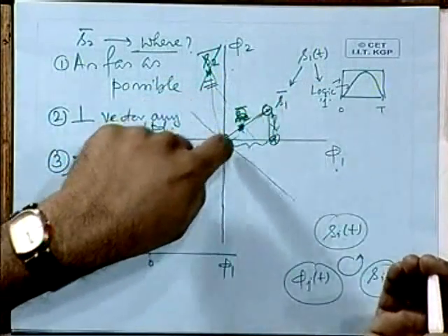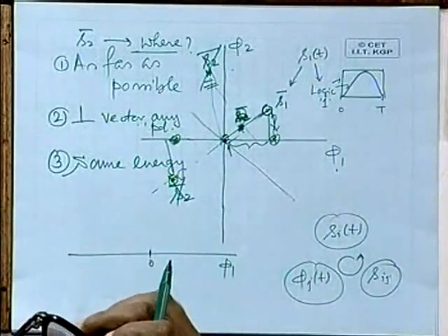The associated issue here, which again I can incorporate in this diagram, is the issue of average energy per symbol. Can I talk about that also in the signal space description? The moment I choose my points in the signal space, I know the energy associated with each symbol or each signal, and usually, as I started in my discussion, in my assumption that all the symbols are assumed to be equally likely, we assume that, isn't it? So, I can talk about the average energy per symbol, even the probability of occurrence of each symbol, and hence the average energy, and then by considering a large period of integration, I can even talk about the average power of transmission, average transmission power, is it not? This transmission power is a very important issue.